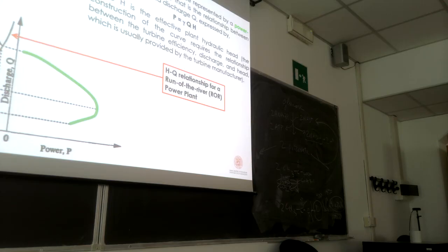Okay, so the power is what? 10,000 Newton divided by cubic meters times cubic meters per second. So Newton divided by second, per meter. So Newton meter, joule, divided by second, watts. Okay? Which reads also 10 kilowatts.